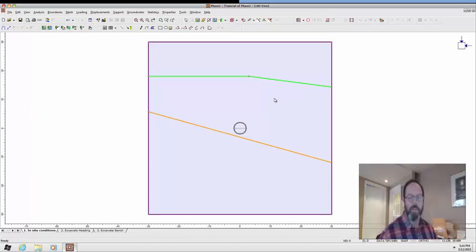You want to have the most refined mesh that you can get without being excessive and leading to excessive calculation times. And you also want to make sure that the mesh is finest or most refined in the areas of the model that you are most interested in. And typically, those are regions where there's high stress gradients or high stress changes. Around a tunnel, the stress gradient is highest in the near field of the tunnel, where the stresses are going to be perturbed. So you want to have a lot of refinement here.